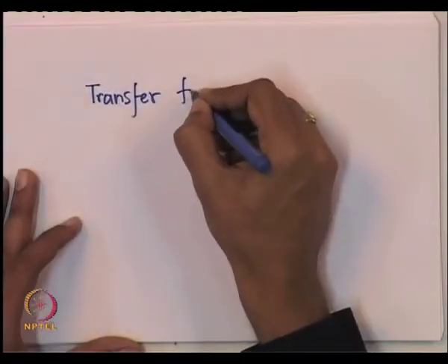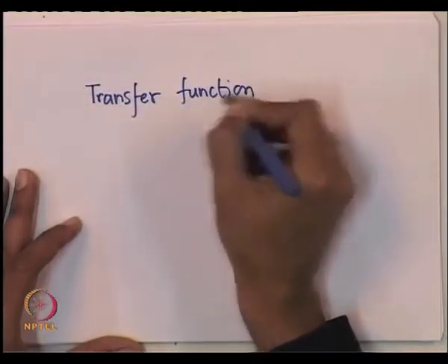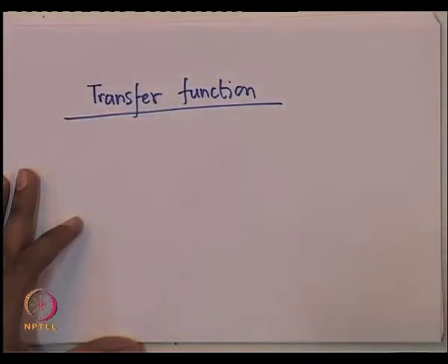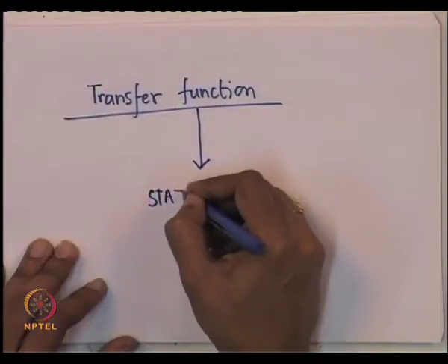whenever we have a transfer function, can we obtain the state space representation? So, if I have got a transfer function representation of a dynamical system, in fact, that is what I have got right now. If I actually do these frequency response tests, I can infer a particular transfer function of a synchronous machine on the d axis with the field winding shorted. So, the question is, from the transfer function, can I get back the state space?